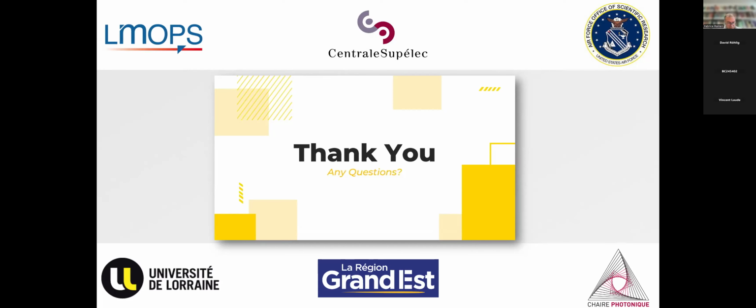So the reservoir computing architecture in itself is a trade-off, in the sense of accuracy. You keep the input weights and the reservoir weights fixed, but then your accuracy is not as high as a fully trained CNN or other digital neural networks. But it still captures quite a bit of information, and it's good enough for temporal sequences. Reservoir computing has been applied across the field in all sorts of machine learning tasks, and it has shown incredible performance. This means that for some tasks, you don't need to train thousands of recurrent weights with backpropagation, which is very computationally heavy and expensive. And this architecture favors hardware implementation, which again means energy efficiency.